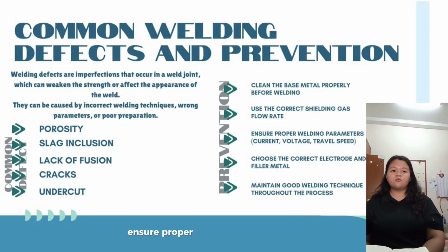Ensure proper welding parameters, including current, voltage, and travel speed, are set correctly. Lastly, use the correct electrode and filler metal for the specific materials you are welding.